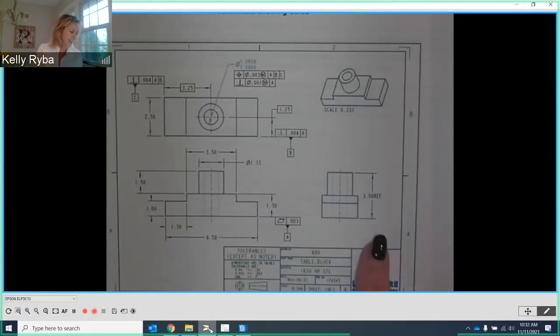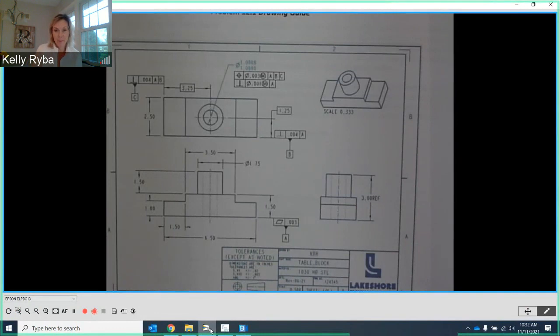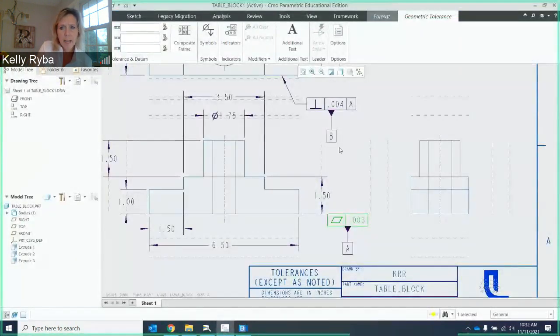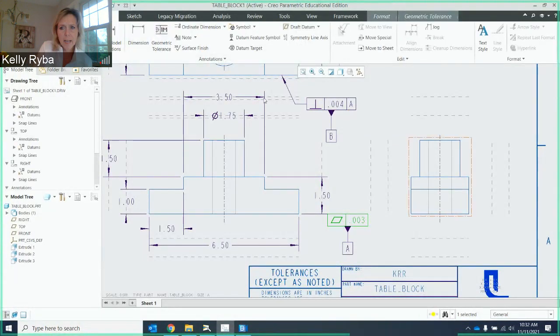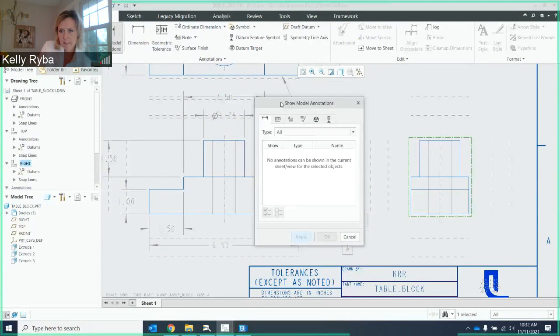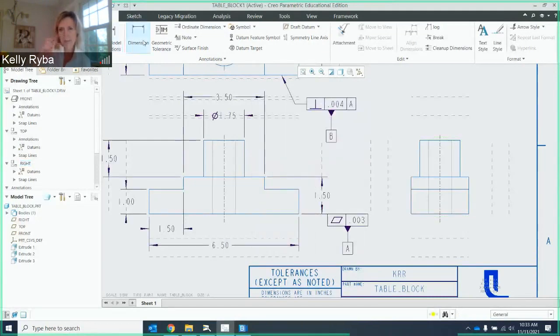I think you could get away without it by putting the reference in there, but the drawing said they wanted 3 views, so I think it's good to do that. So add just a reference dimension over here in that right side view. Back to Creo, if I go back to annotate and put the dimensions in that view, it's not showing any, right? Because we've used dimensions already in the other 2 views. So I'm going to hit cancel here, and I do need to add a manual dimension.